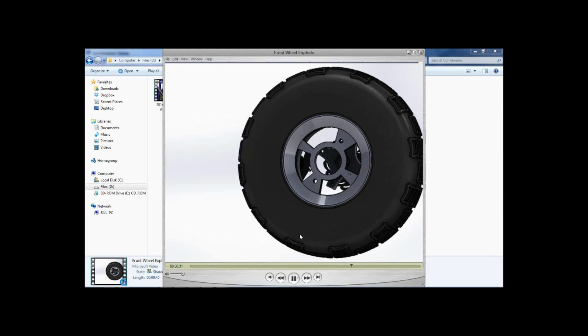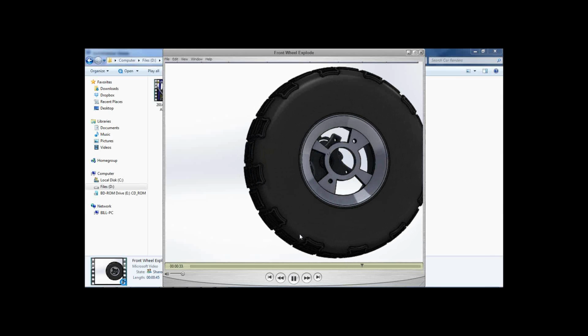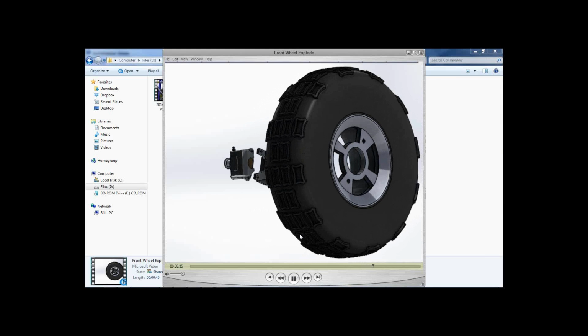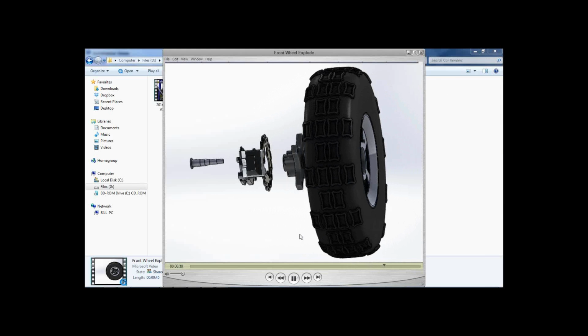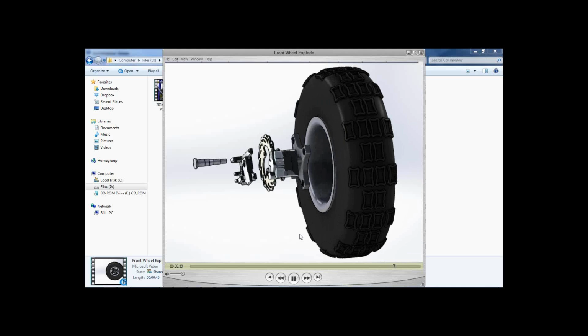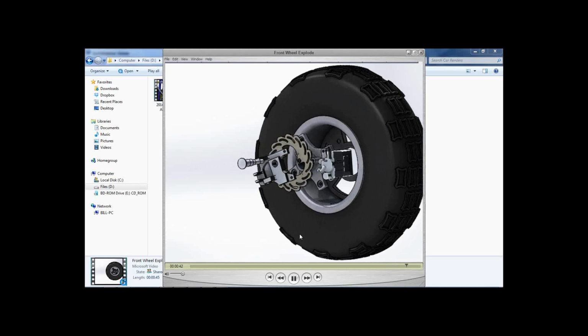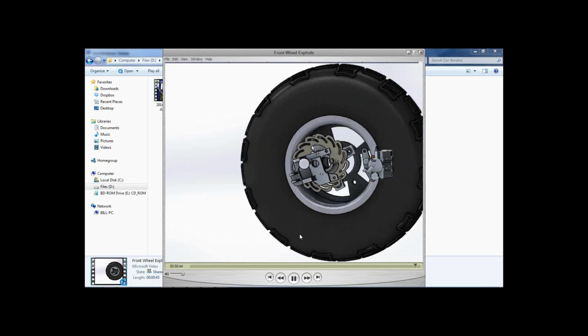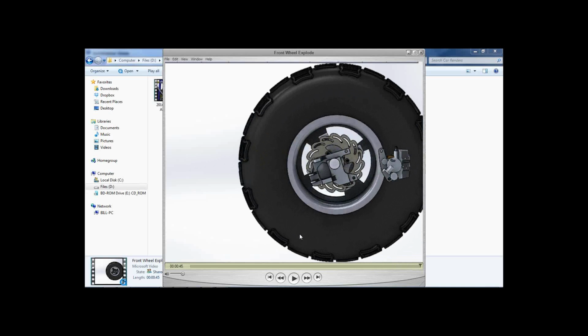But of course, once you get on a mill or a lathe, it just isn't. So one of the things that we went through with our upright this year is how are we going to make it? And it went through quite a few design iterations before we got to something that was possible to CNC. So that was a rotated view of our wheel hub.